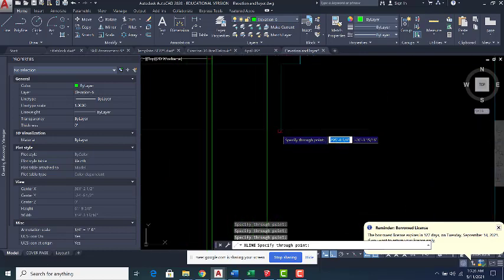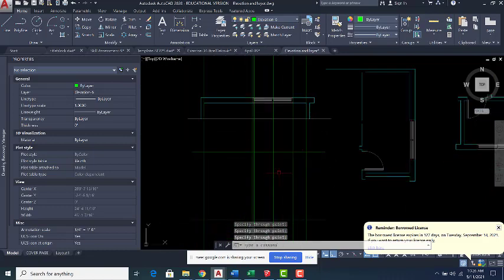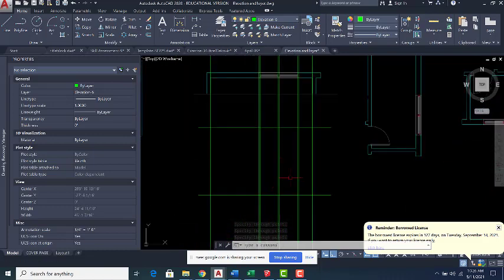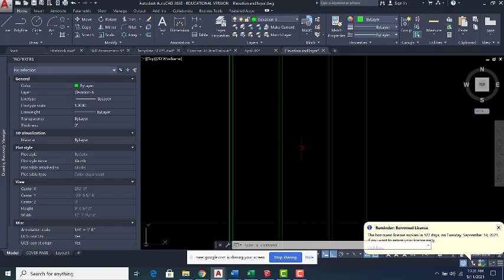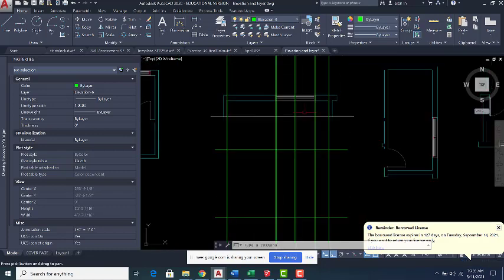Again, there is no need, if you are in an architectural firm, you had to do the wall thickness. Here, we just ignore that, we just do the interior of the wall. So now that I have this part, again, to make your life easier, go and change the layer of each of these lines. Otherwise, you are looking at many green lines and you don't know, okay, what should I do? But here it's really simple.